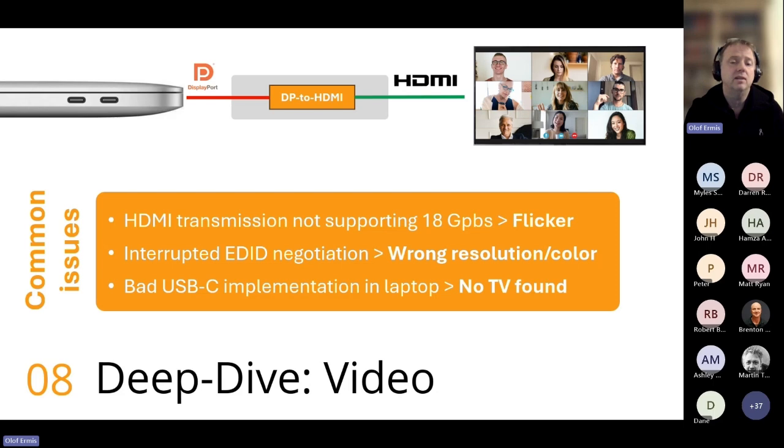It could be a long HDMI cable, more than 7 meters, and then HDMI 2.0 bandwidth becomes a bit on the edge. When you normally insert an HDMI cable directly into a laptop, there is a built-in feature in HDMI that does a signal training to test the capability of the solution, and then the laptop selects a resolution that it can safely run over the HDMI cable.